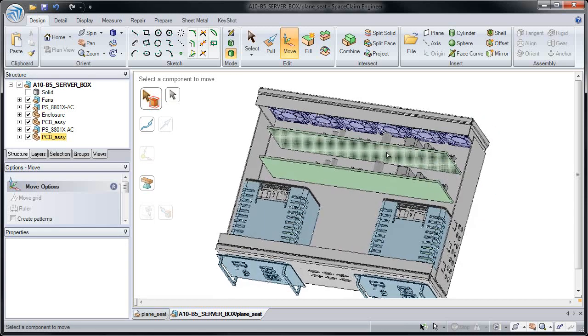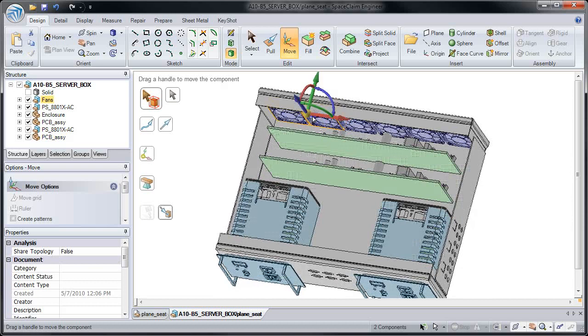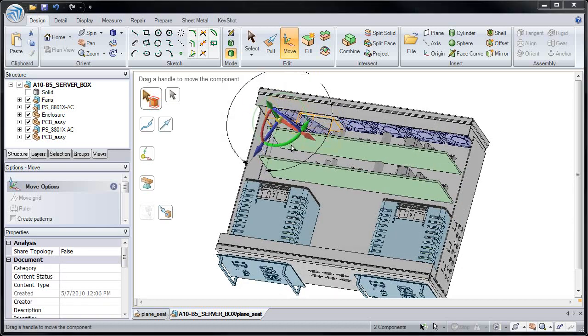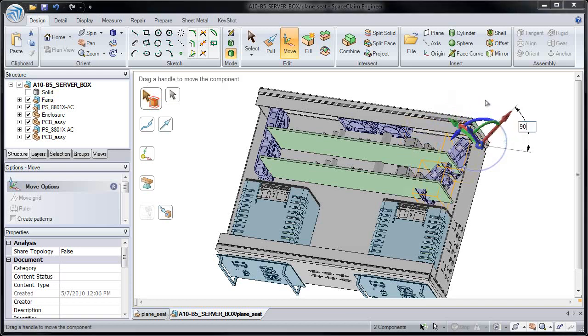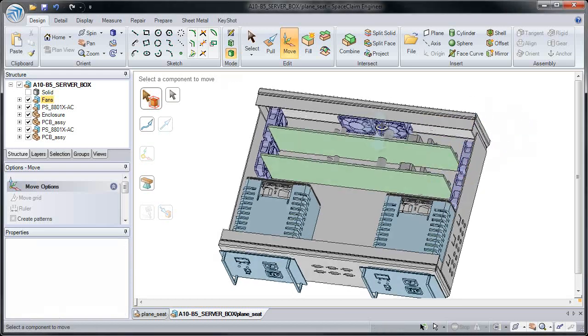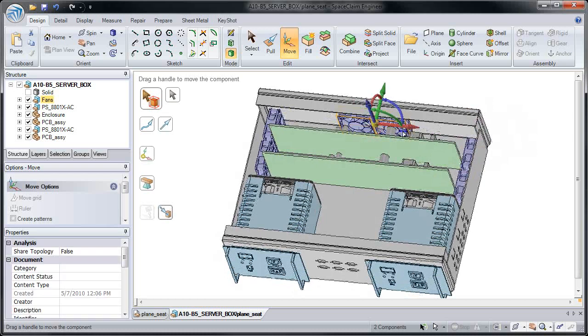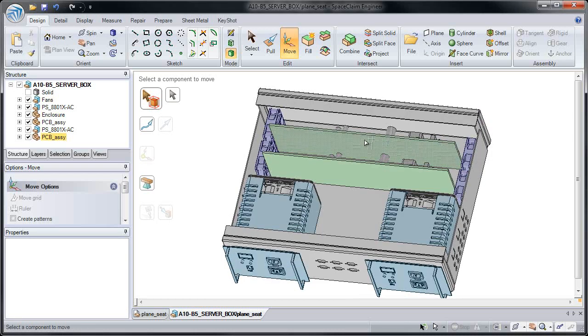By placing our circuit boards vertically, not only will it be easier to run air across them, but it'll also be easier for assembling and replacements later on down the road. In fact, by rotating our fans and running the air across them, we could even possibly get rid of one or two and reduce both cost and weight.